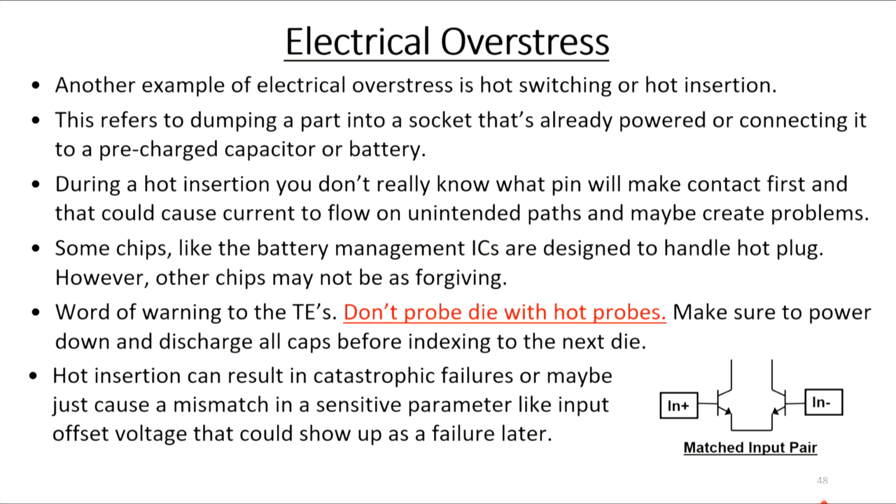A word of warning to the test engineers out there: don't probe die with hot probes. Make sure to power your test circuit down, and discharge all capacitors before indexing to the next die. You don't want to bring hot probes down. You'll end up blowing out a whole wafer, perhaps. Hot insertion can result in catastrophic failures, or maybe just cause a mismatch in a sensitive parameter like an input offset voltage, which could show up later as a failure.